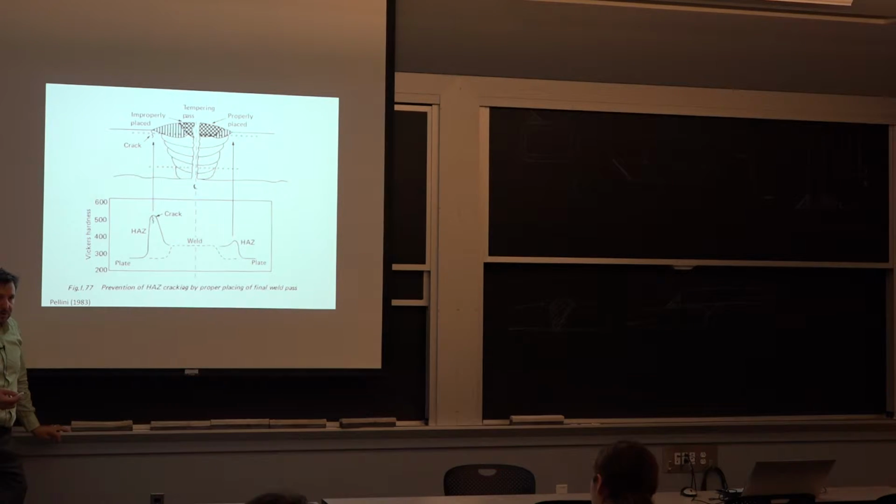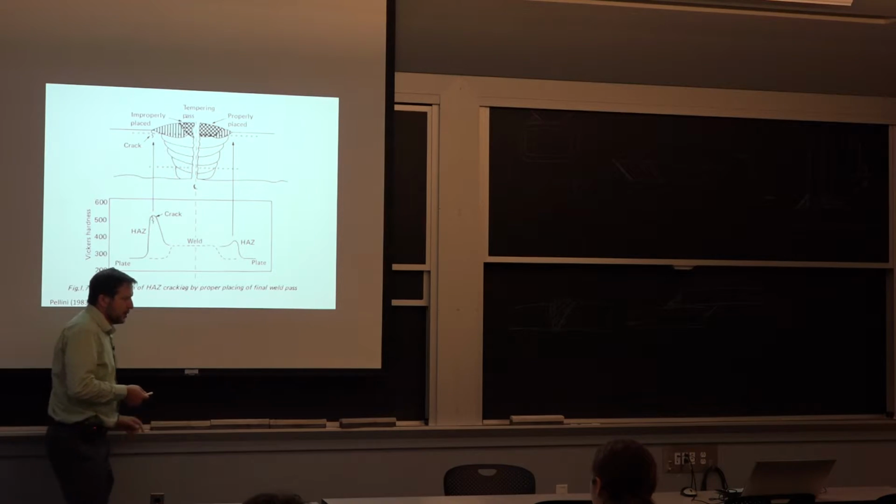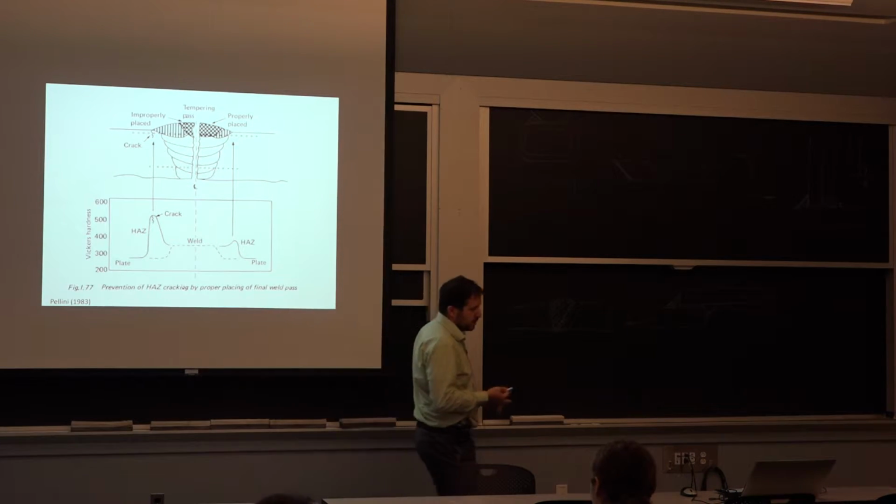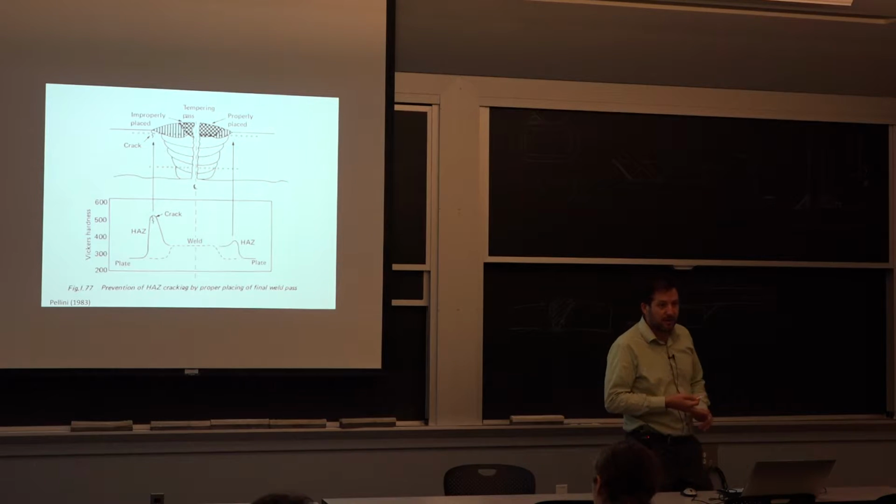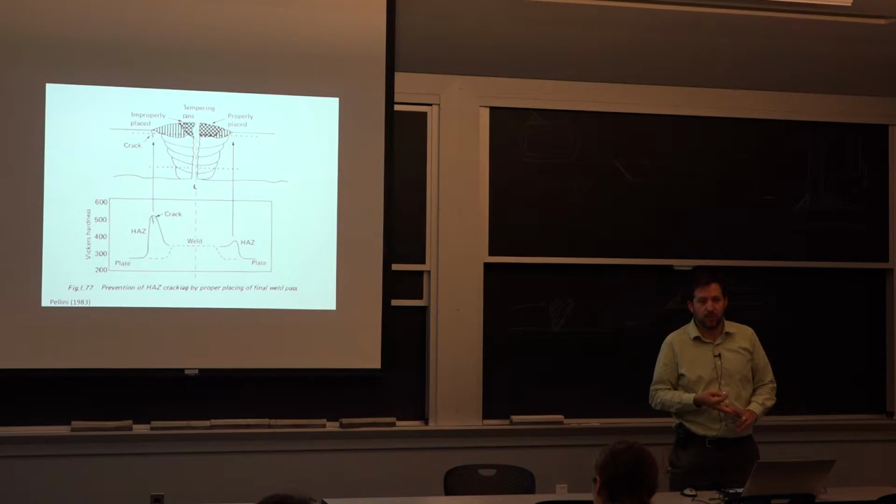If we go through that martensite phase, then we get into much lower ductility. So it's a place where cracks do tend to initiate, but this is for completely other reasons than residual stresses or the geometry itself. You change the material permanently. So between those three factors is where we get our factor of 10 if we're loading transversely.